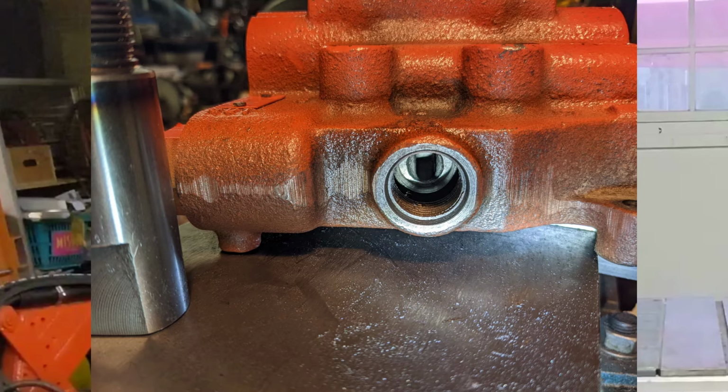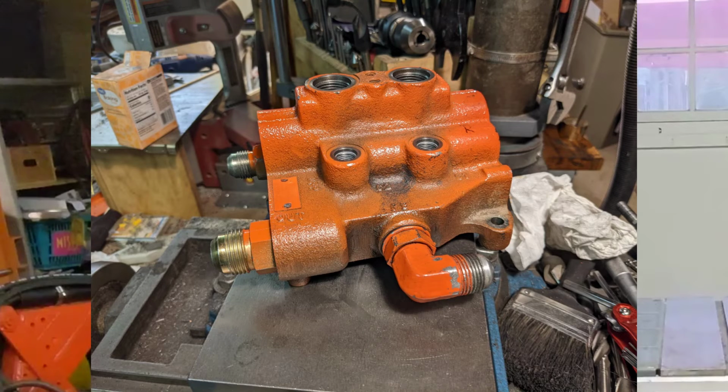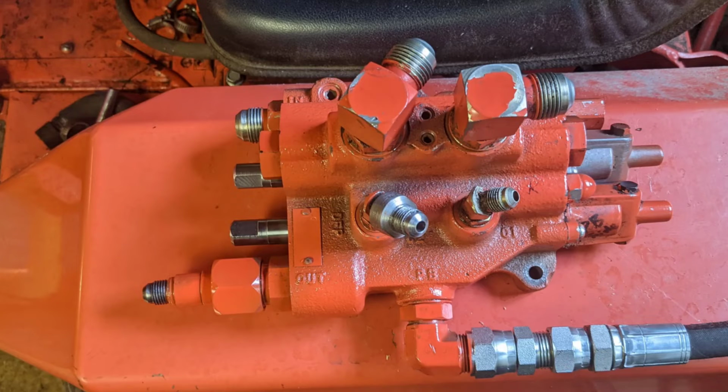With the inner hole complete, I drilled the outer wall big enough to use the reamer, then ran the reamer in using plenty of lubricant and very slow spindle speed. Finally, I ran the tap down into the reamed hole, again with plenty of lubricant. So now the machining was complete. I cleaned out the valve body, washed out any grit and swarf with compressed air and multiple baths of solvent, and then I reassembled and applied a final coat of paint. Now there's no easy way to pressure test this without reinstalling it, so I guess that's what we're doing next.